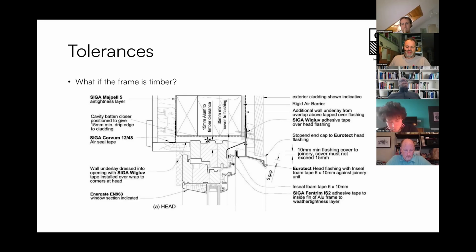And when they use prefabricated window elements as a window facade being entirely placed within the opening from ceiling to ceiling, so it's an infill, they used to use either aluminium window systems or wooden window systems, but they add a piece of timber around the entire circumference of the prefab element that fits within the tolerance, often intentionally made a little bit bigger.